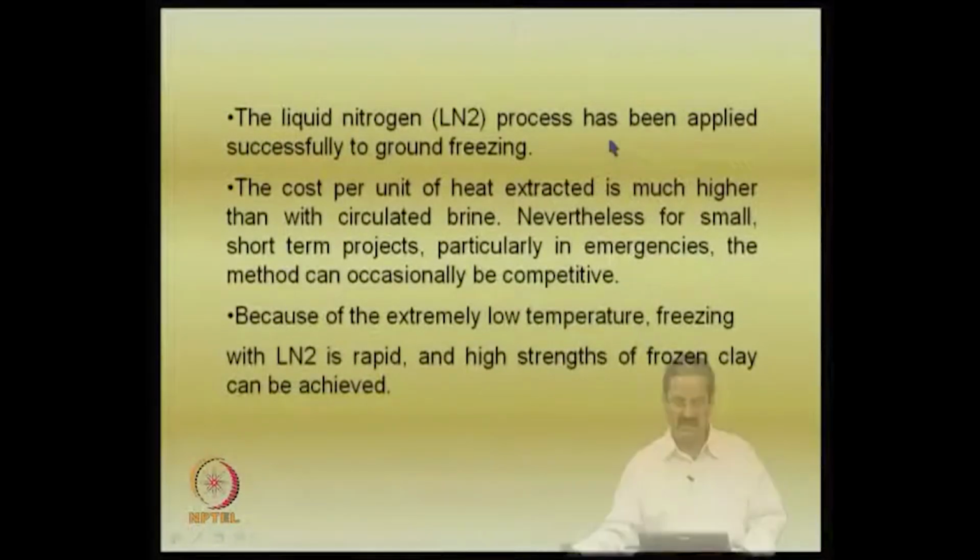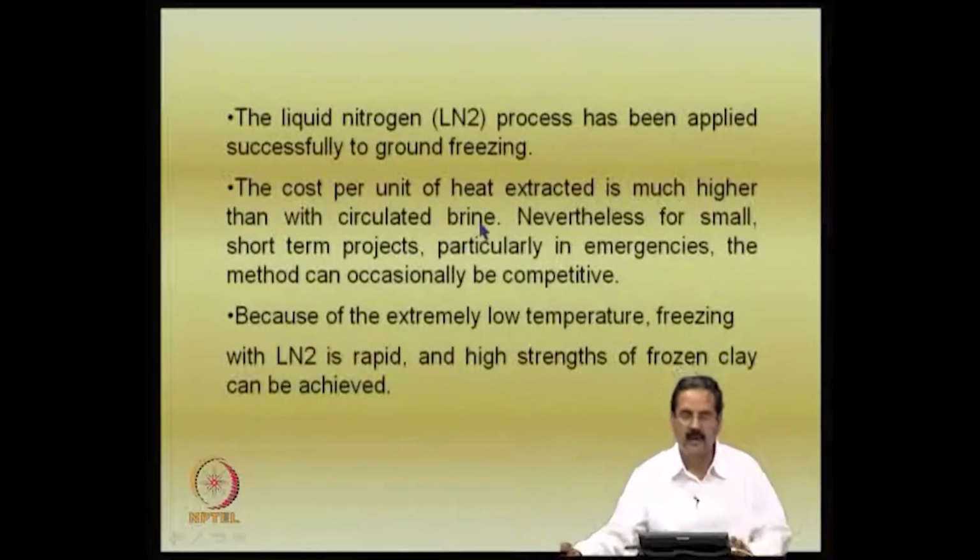The liquid nitrogen process has been applied successfully to ground freezing in some places, and the cost per unit of heat extracted is much higher than with circulated brine. The brine solution is somewhat cheaper compared to liquid nitrogen. Nevertheless, for small short-term projects, particularly in emergencies, the method can occasionally be competitive. Because of the extremely low temperature, freezing with LN2 is rapid and high strengths of frozen clay can be achieved.